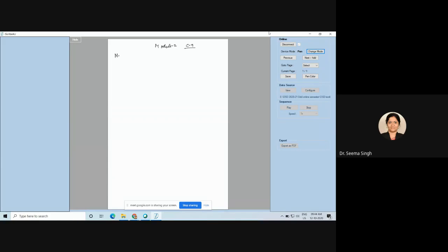First thing we will do is multiplexer ICs. And we are going to see 4 types of IC. Number 1 is 74153. You will have to remember these IC numbers. 74153 is a dual 4:1 IC. Dual 4:1 mux.